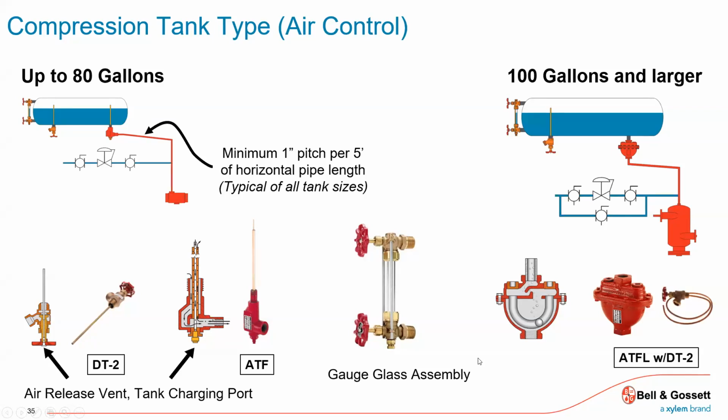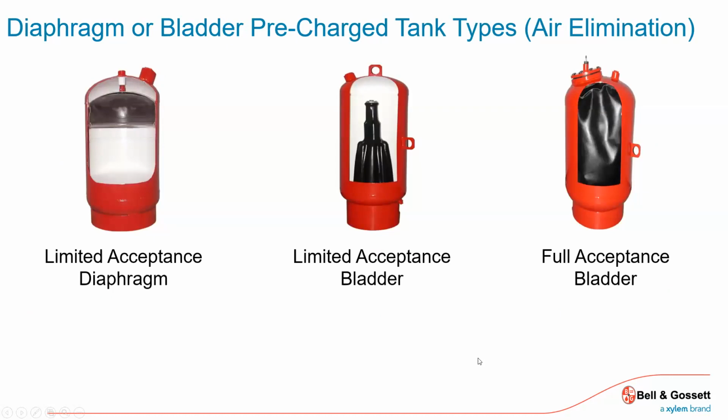When you first put that system in, that system's cold. And the other thing is this had to be mounted up high in the rafters, up at the ceiling of the mechanical room above the heat source, the boiler, because the air was going by buoyancy, by gravity. You couldn't take that tank and put it down on the floor, because how in hell are you going to get that air to go down? It wouldn't. Here, I don't need that air. I want to get rid of that air. So I can put that tank wherever I need to.